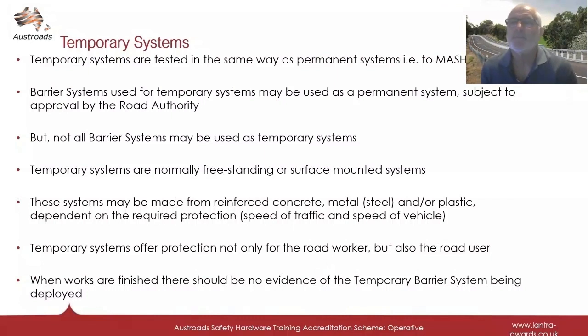Temporary systems. Temporary systems are tested in the same way as permanent systems, i.e. to MASH. Barrier systems used for temporary systems may be used as a permanent system. However, this is subject to approval by the relevant road authority, but not all barrier systems may be used as temporary systems. Temporary systems are normally freestanding or surface-mounted systems. These systems may be made from reinforced concrete, metal, steel, and/or plastic, dependent on the required protection, speed of traffic, speed of the vehicles, etc.